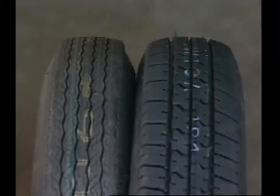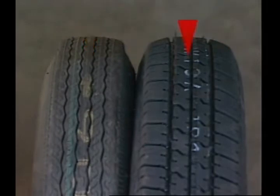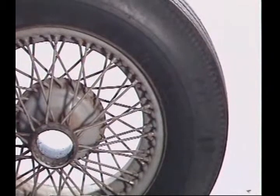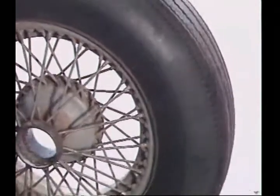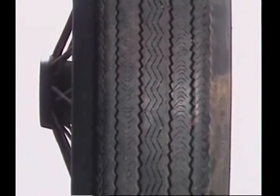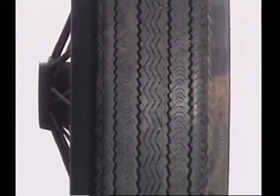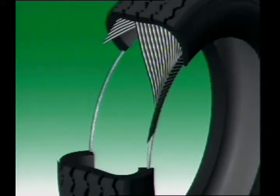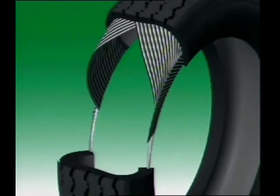Two types of tyre construction are common: cross-ply and radial ply. The cross-ply tyre is the older form. It is also called a bias ply or conventional tyre. It is constructed of two or more plies or layers of textile casing cords positioned diagonally from bead to bead.